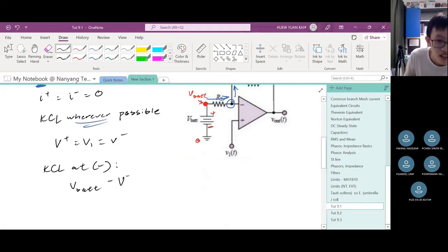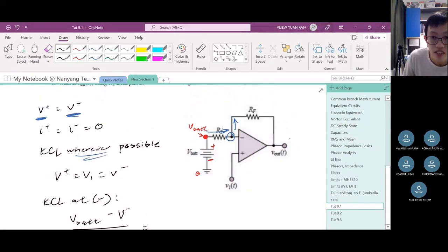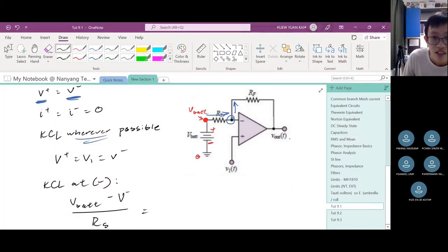Yeah, V minus over the resistance. So it's Rs. Right? V start minus Vn divided by the resistance equals to the current going out. So this one is the one going up, right? So where do we start and where do we stop? We start over here and we end, right? Our current travels through and then we end at this node.